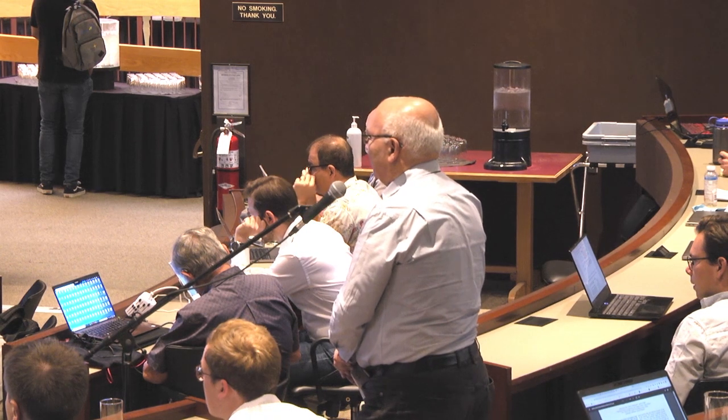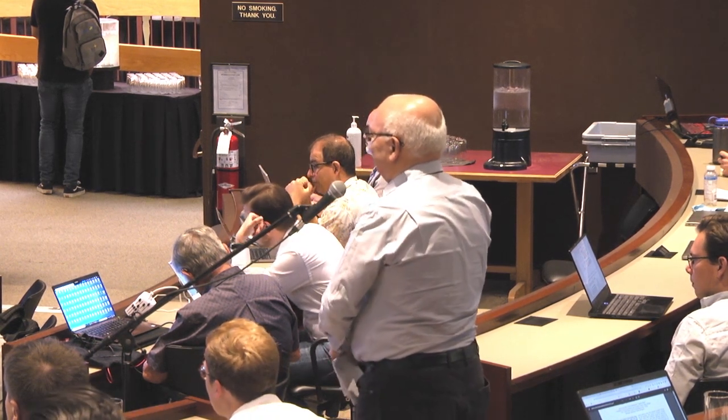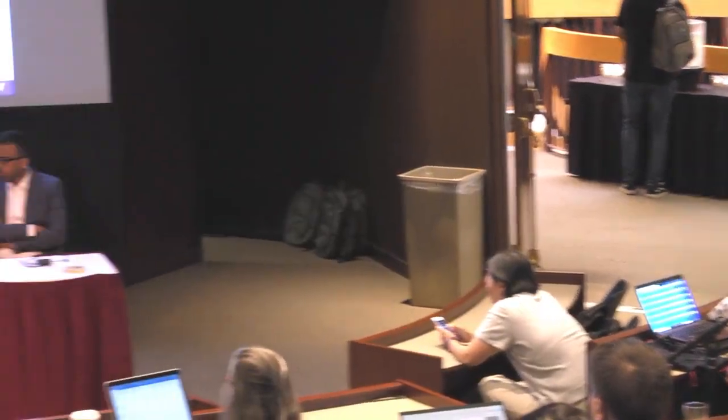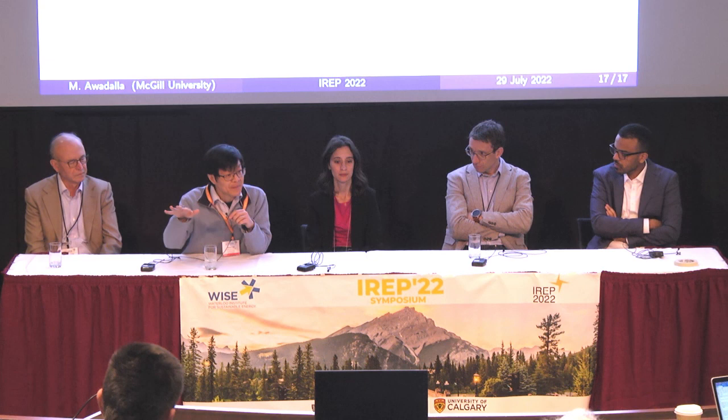Yeah, that's right. I think that there's nothing new in my paper. I think the new thing is perhaps a unified approach to explicitly think about three-phase devices, and they have this separation of internal and external model. I mean, this idea is spread around different papers. But I think if we don't explicitly do that, we often make assumptions. For example, neutrals are grounded. They may be grounded with zero grounding impedance, and so on, which sometimes we're actually not aware of. And therefore, we will get equations that are simplified, but may or may not be accurate enough for your problem.